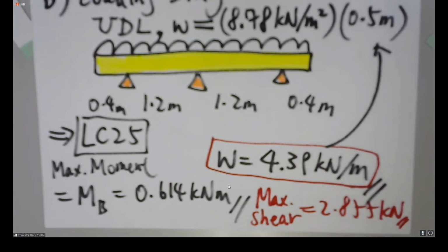Okay, for the beam formwork tutorial practice, you can go to Canvas and download this PDF under the folder week 3, slab formwork and beam formwork. So you have question 1 asking you to draw the loading diagram for this joist. So you have the concrete beam. If you consider only the vertical load, the beam is supported by plywood and then by the joist.